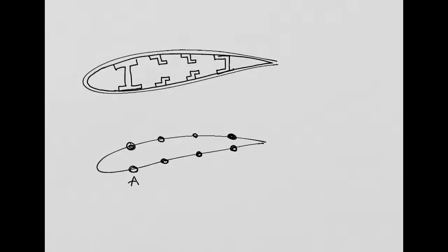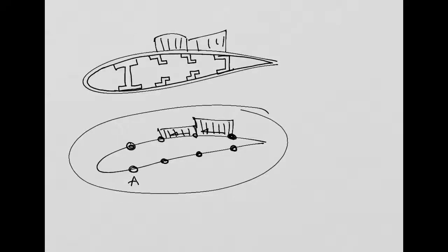So while in this fully effective cross-section we define that the shear flows have, for example, quadratic distribution, or they can have linear distribution, or whatever, right? These complex distributions. In these idealized cross-sections, the shear flow will always have constant distribution between two booms. Here it has this constant value, here it is also constant, but maybe a different value. So the model is much simpler. Okay? So we are going to learn how to do this kind of idealization to build an equivalent model which is structurally equivalent to the original cross-section.